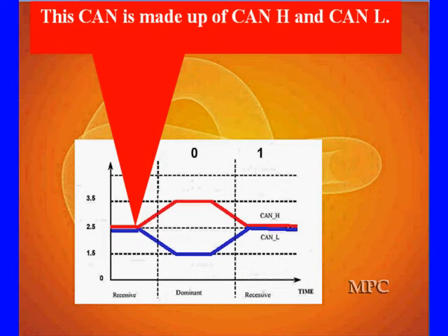We're going to use a CAN signal. This is high-speed CAN made up of 2 wires. One wire is called CAN H and one is called CAN L. Now, don't confuse CAN L, CAN H with high-speed CAN and low-speed CAN. We have 3 flavors of CAN when we get there. We've got low speed, medium speed, and high speed. This is the high-speed CAN.